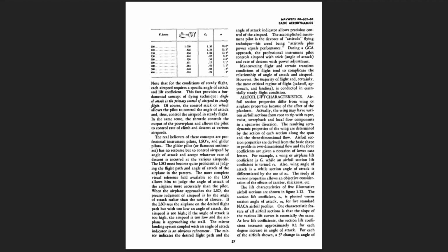During a GCA approach, the professional instrument pilot controls airspeed with stick, angle of attack, and rate of descent with power adjustment. Maneuvering flight and certain transient conditions of flight tend to complicate the relationship of angle of attack and airspeed. However, the majority of flight and certainly the most critical regimes of flight, takeoff, approach, and landing, are conducted in essentially steady flight conditions.